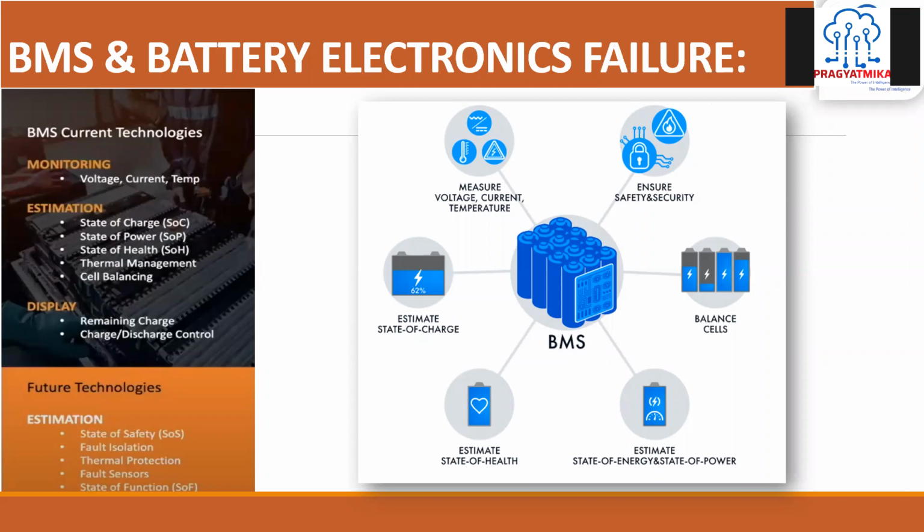And then we have BMSs with state functions, that is the state of charge, the health, the thermal management, the temperature, the balancing, all these things the BMS is doing. So whenever we are going to make a safe battery design, and a performing battery design, we should always be looking towards a BMS which has state functions at least, so that you can get behavioral knowledge about your battery pack and the different parameters of your battery pack.